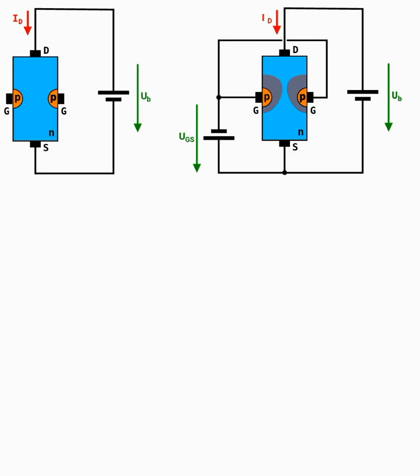Now due to this, on the P-type semiconductor you have a negative voltage applied, and on the drain side of the N-type semiconductor you have a positive voltage applied. So N is connected to the positive and P is connected to the negative. So this PN junction towards the drain and the gate is reverse biased. That's why we see there is a depletion region shown in the figure.